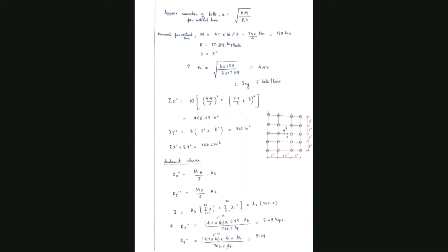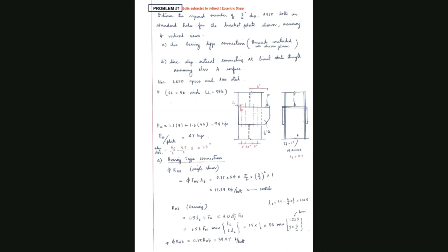And this is the spacing that we were talking about. We had chosen it as 3 inches. Doctor, we choose the S to be 3, right? We didn't calculate it. Yes, I think it must have been given in the question. Probably I missed it. If it's given, I use it. But if it is not given, you have the spacing limitation, S minimum and S maximum. Based on that, you can choose a value. Typically for your course, 3 can be chosen for anything. You can do the calculation just to show, but typically you can take 3 because 3 works for all cases.